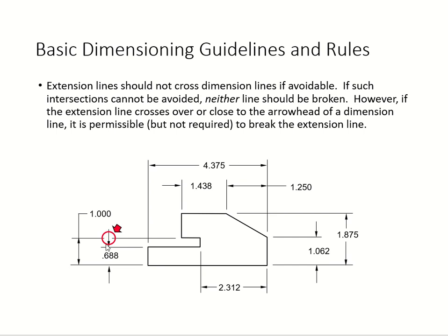Because you can't break the line. It's better to use a continuous line like this. But of course, there are certain exceptions. At that time, you will have to do the crossover, but don't do it. Okay, it's not good. Because it's better that extension lines don't cross over or under the dimension lines.